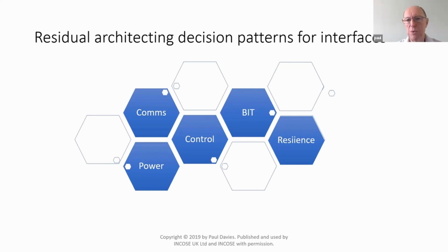Okay, so that's a more distributed architecture. Likewise, power: am I going to supply mains voltage to every individual system element and it does its own down conversion, or am I going to have a dedicated power supply unit that distributes low voltage supplies to each system element, which gives a single point of failure?